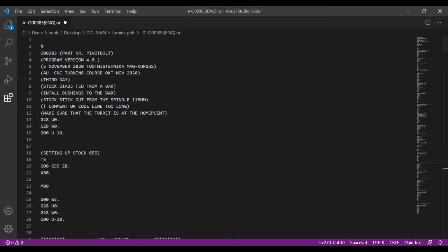Why do we need to understand NC code when I can use CAM? Answer is simple. Sometimes CAM programs have some errors in them, and when you clearly understand what is going on in the program, you can modify it on your CNC's controller instead of creating a new one with CAM software.